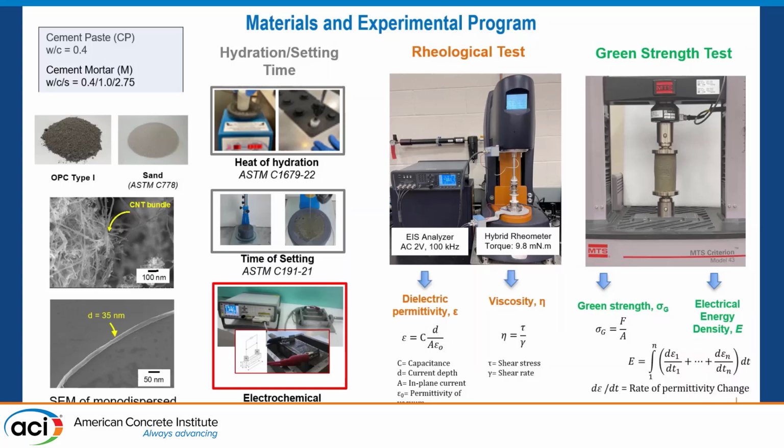We also conducted rheological tests using a hybrid rheometer that measures the viscosity of the material and at the same time the dielectric permittivity through an impedance analyzer which is connected with a dielectric accessory to the rheometer.